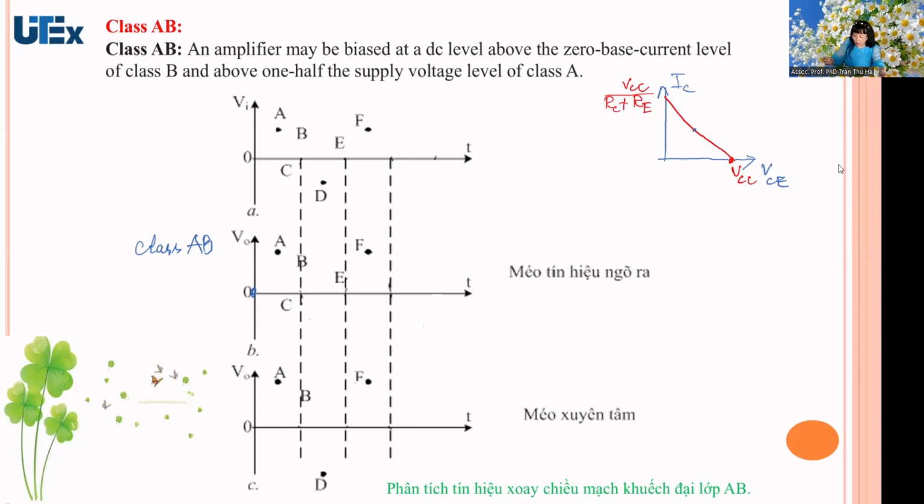And of course, related to the AC energy, we have the green color. This here is AC. We have the AC load line, and we have the DC load line. And we can trust the biasing only, okay? This here is for class A. This here is for class B. And in our situation, this is the Q point for class AB.